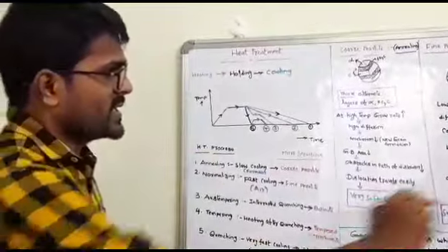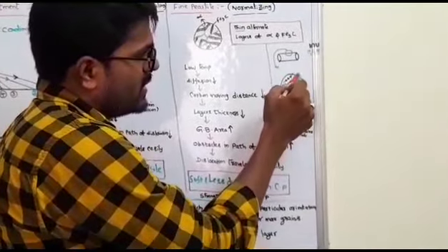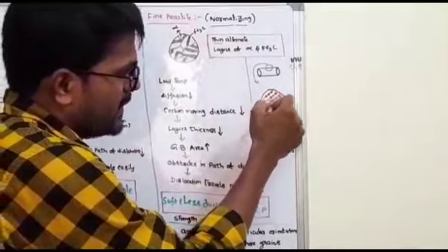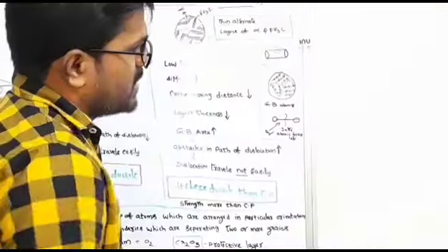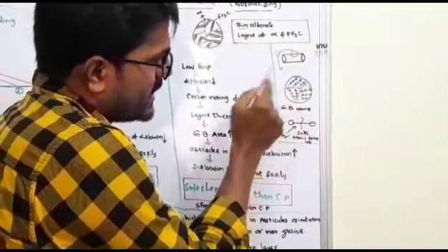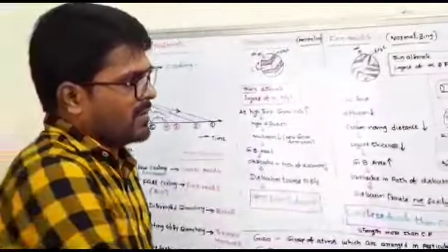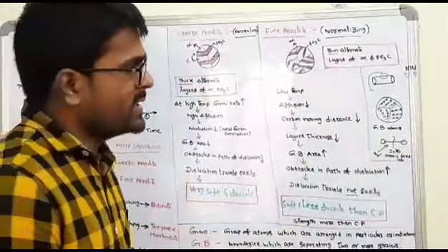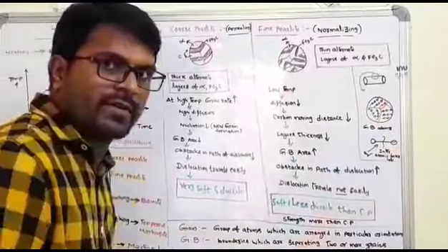In this material science, you see these atoms are in different orientations. If you take the grain boundary atoms, the distance between these grain boundary atoms, that is the bond length, is more. Because this bond length is more, the interatomic forces are very less.